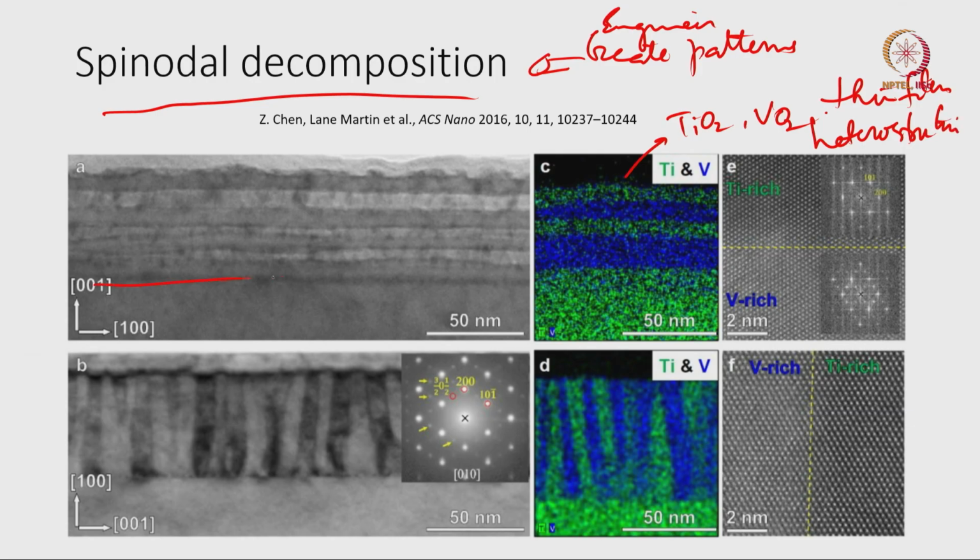Okay. So, on a substrate, something like silicon or whatever substrate it is, I do not remember what substrate this is, right. On this substrate, I am going to deposit a solution of titanium oxide plus vanadium oxide at high temperature, right. At high temperature the alpha phase is stable, right. So, titanium oxide, vanadium oxide high temperature phase or beta phase, right, alpha phase. Okay. So, at high temperature the alpha phase exists as one solution, right. Now, as I keep cooling the temperature down, the alpha phase will then spontaneously split into titanium oxide rich and vanadium oxide rich regions, like you can see here, right.